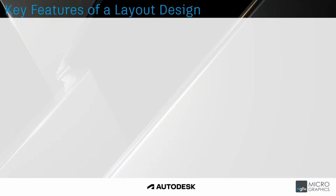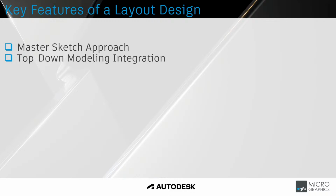Key features of the layout design in Inventor. One of them is the master sketch approach, where a 2D sketch is used to define the key geometry, dimensions, and relationship. It acts as a guide for creating and positioning parts in the assembly. Top-down modeling integration, where layouts can serve as the driving framework for the top-down assembly modeling. Components can be created and constrained based on the layout.